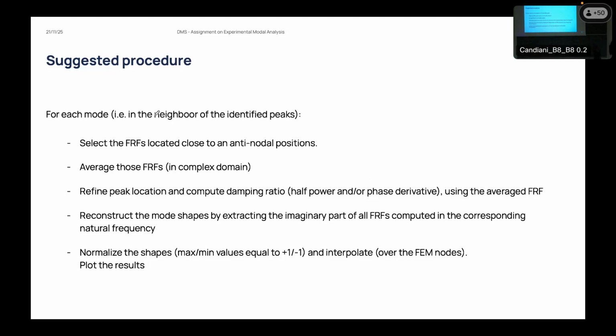If we consider this case, and we think that this sensor is located exactly over the mid-span, since the mode shape of the second mode will be something like this, if I'm looking at the frequency response function that is located, let's call this location number 1, if I'm looking at G1K, the amplitude, I will see a peak for the first natural frequency.